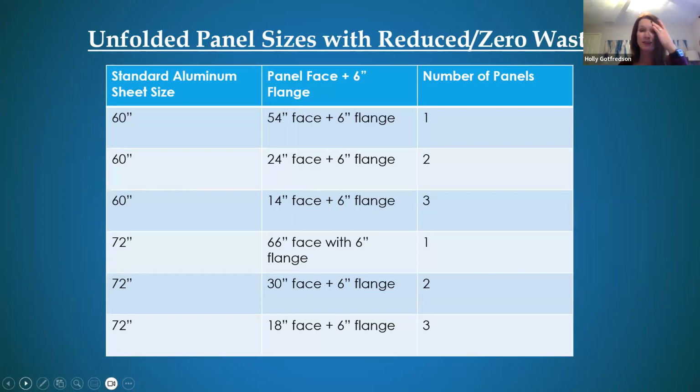Now, I didn't mention 72-inch wide, and that was on purpose. You might remember in 2017, 2018, when we had the metal tariffs, 72-inch wide had a pretty long lead time before that, but once the tariffs were implemented, we had a lot of peaks in the metal market. The scarcity of that material increased. And then add COVID to the mix, and it increased even more. So it is available, but please talk to your panel manufacturer before you commit or really get married to the idea of having this size panel module, just to make sure that that material and that width is available.